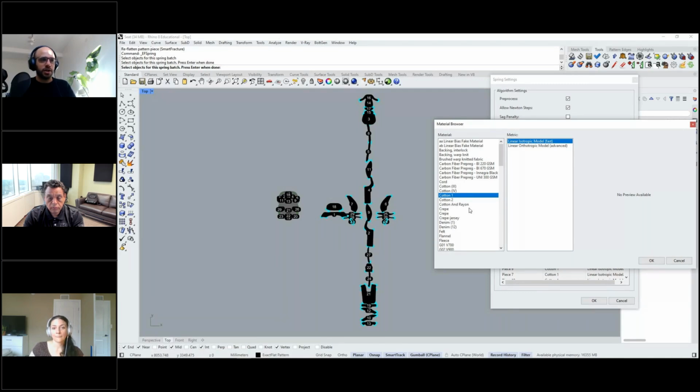So the material that we choose here is going to affect the shape of the flat patterns. If the material that you're looking for is not within this list, we do have an agreement with a lab in the US where you can send a sample of this material and it can be tested. So within 5 to 7 business days, you'll be able to add your own specific materials to your material library if needed. That has a cost of around $50 per material sample, so it's really cheap. And that way, you'll be able to simply add your own materials. Nevertheless, I would say that most of our customers get away with using the materials that we already have in the list. I'm going to go for laminate material for car seats in this case.